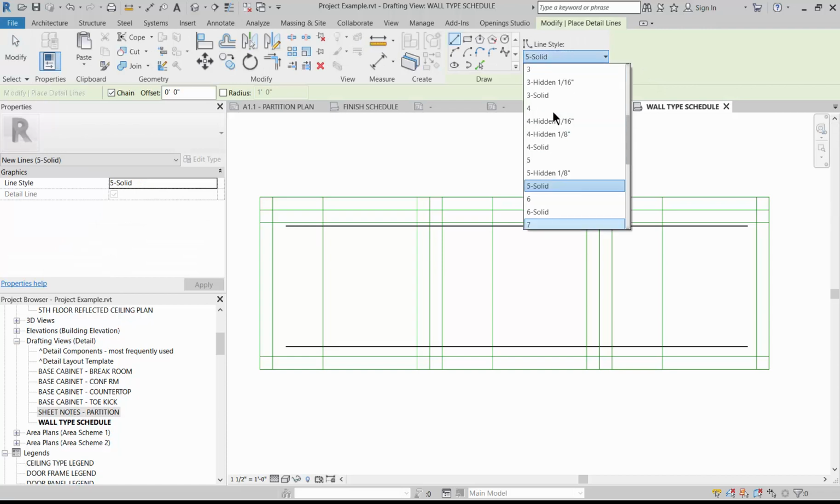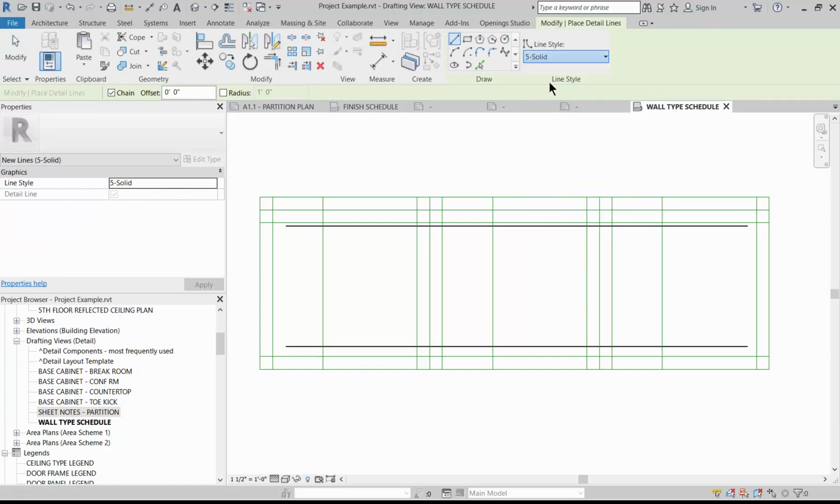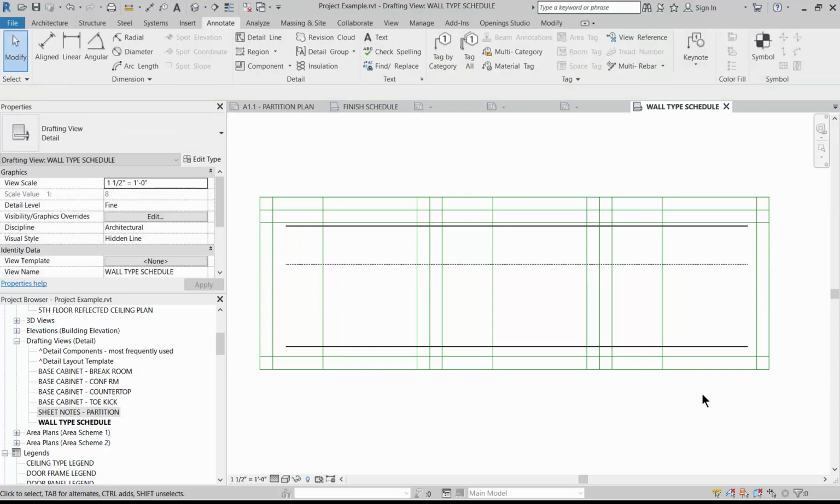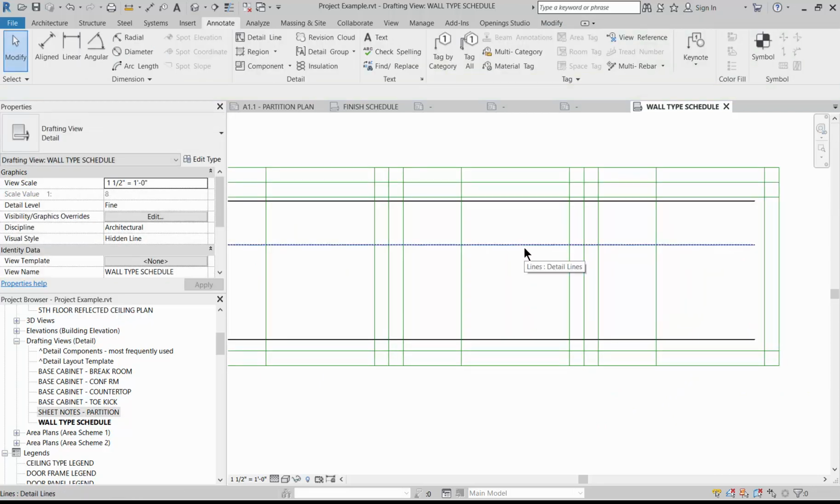So I'm going to use a thicker hidden line and set that off slightly. This is showing where my typical ceiling height is. So that's for ceiling type partitions. The through ceiling partitions will go just through, and then deck height partitions will go all the way up top. And we'll use the break lines in between.